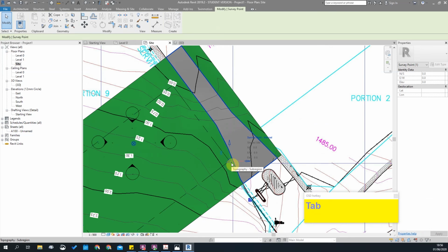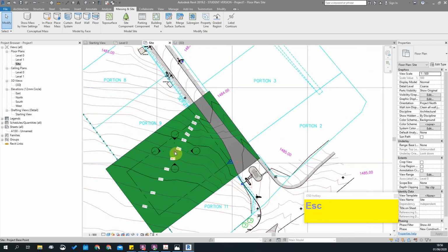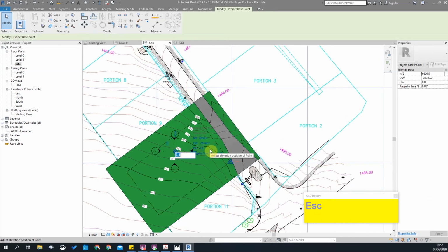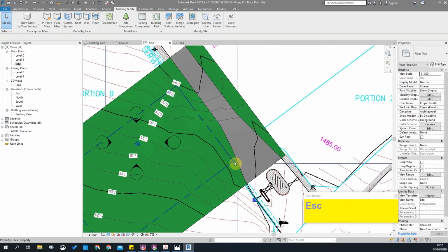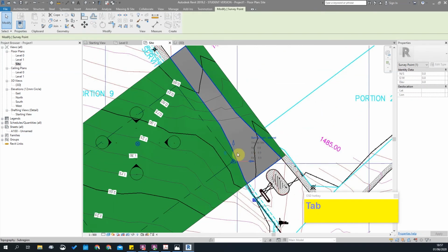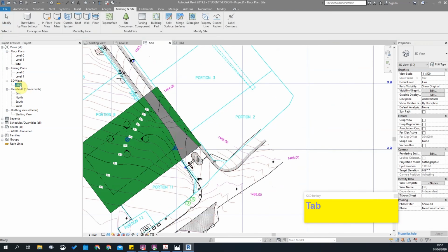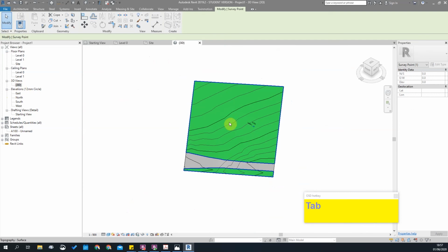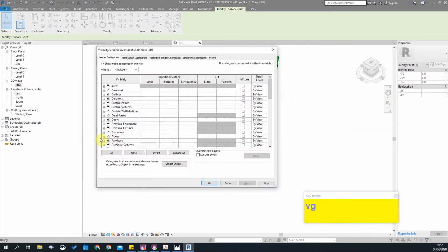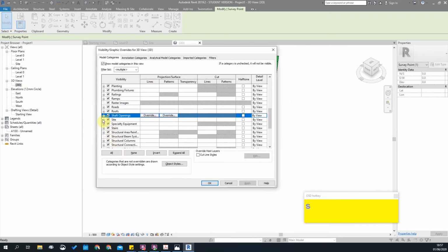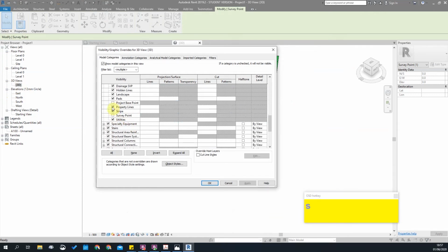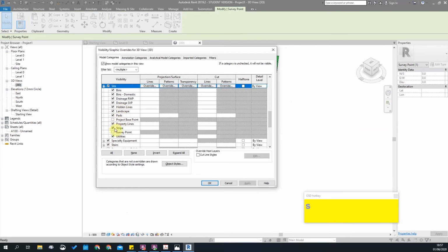You've got 2 options. For this option, what I would do is change this elevation. I know, you drop this value, my apologies. This value you drop. So you're going to go to 3D view, and go to VG. You're going to switch on your site information, and switch on your survey point only. Survey point, press apply.